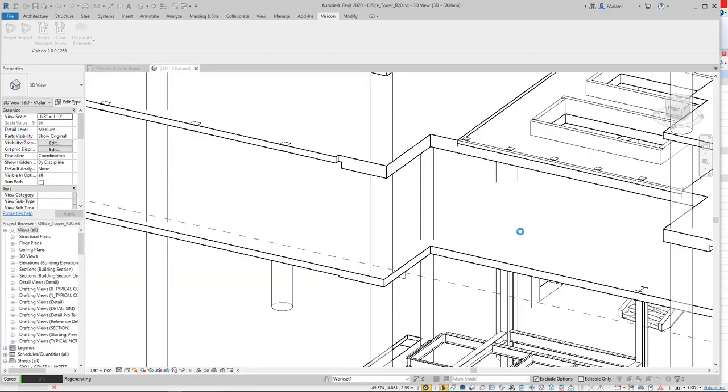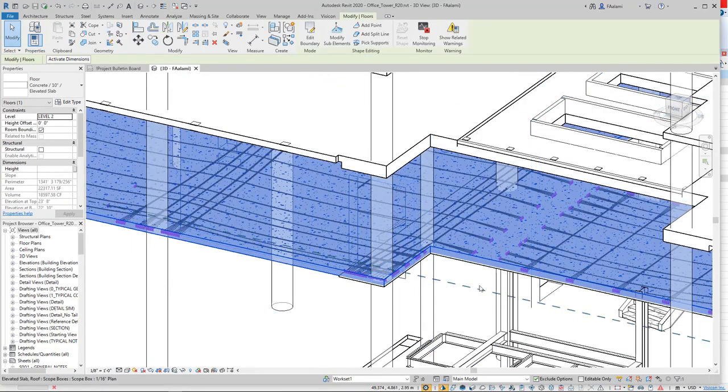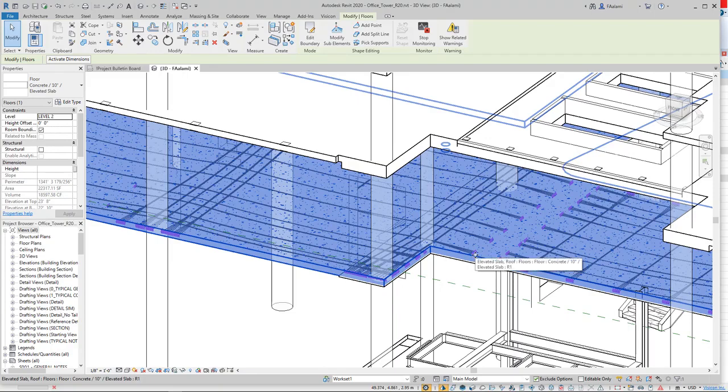Once the import is completed, you'll see that it's updating the Revit model with the imported geometry. To verify that the tendons are actually in the Revit model, we'll select one of these slabs, and you can clearly see that the 3D tendon geometry has now been imported. My recommendation would be that you actually create the 3D tendons in a separate, dedicated file and link the tendon model to your primary structural model or architectural model. Each of these tendons is represented as a generic 3D mesh object in Revit and will show up in any sections or sheets that you need to display them in.